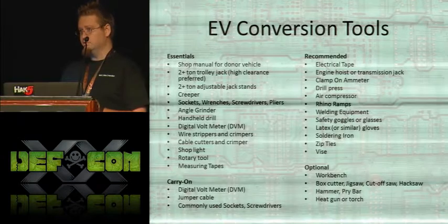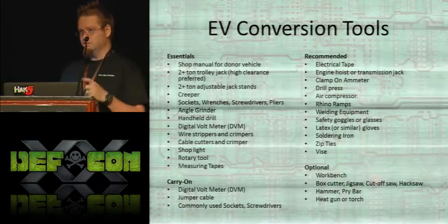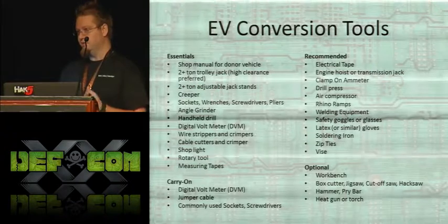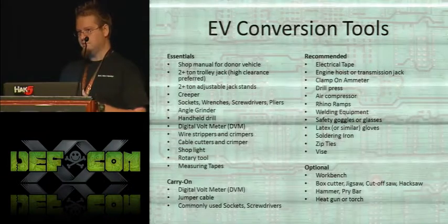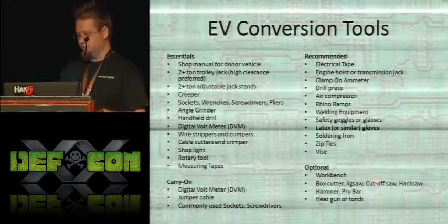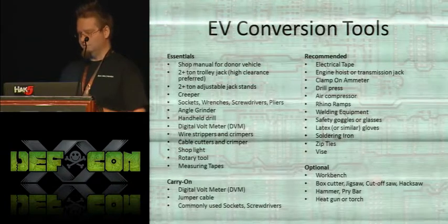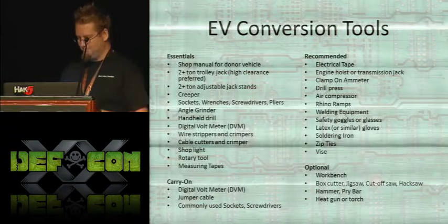Also, on all your tools, you should put some insulation around the handles. You don't want to be using a tool and have it smack against a battery and short things out, because then you've created a welder that you're holding. So I, of course, didn't bother to do that until I had my first high voltage event, and then I went and did it.